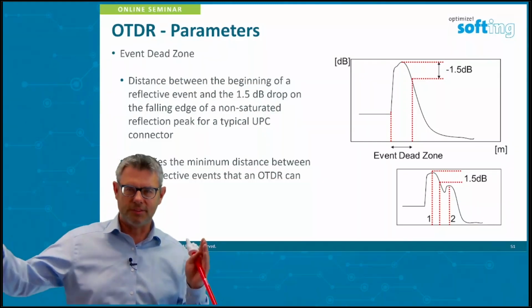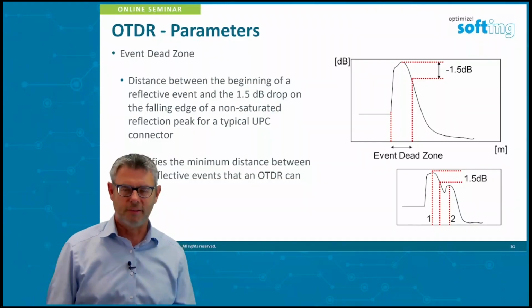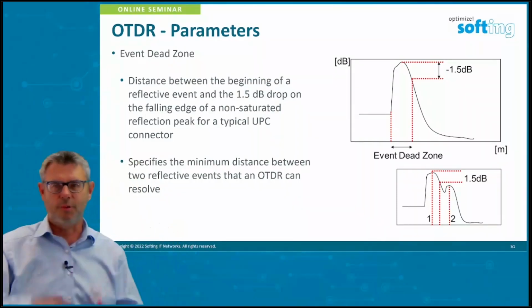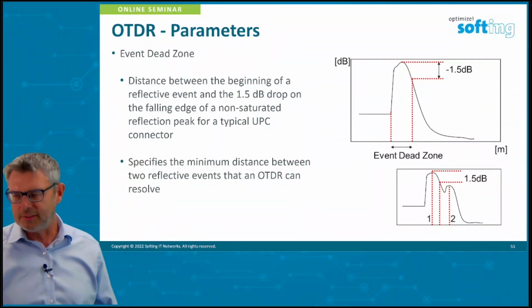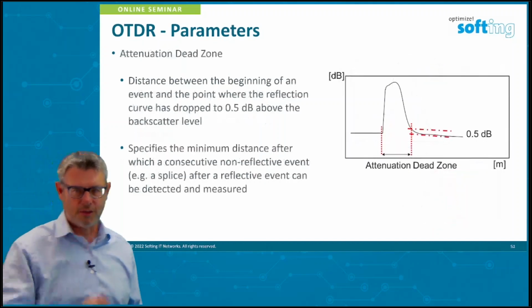Okay, if the dead zone is too long, you wouldn't see these connectors in between. So you would only see one funny pulse and that's it. The second important dead zone is the attenuation dead zone.